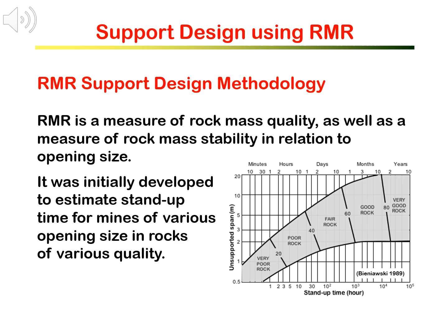By using RMR, we will be able to estimate the stand-up time for a specific unsupported span in normal underground support installation. This is rather useful for planning the excavation cycle in terms of advance length, stand-up time, and temporary support installation.